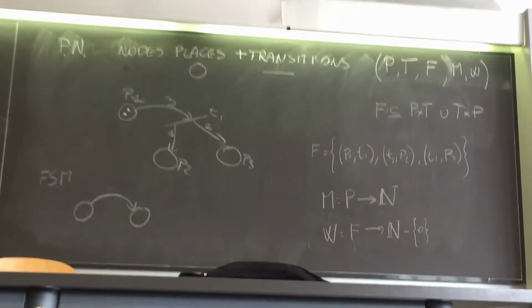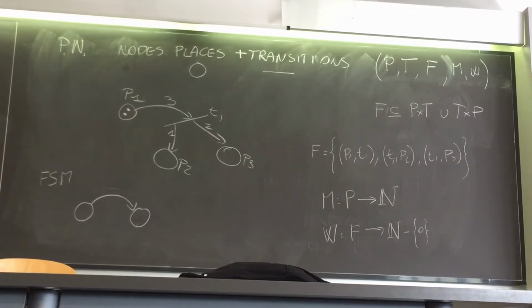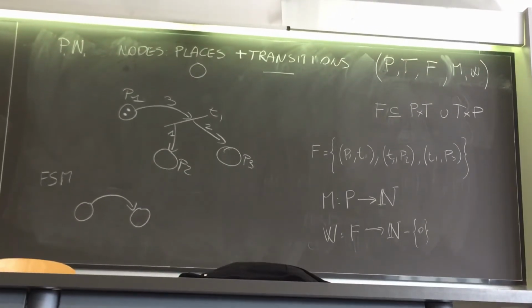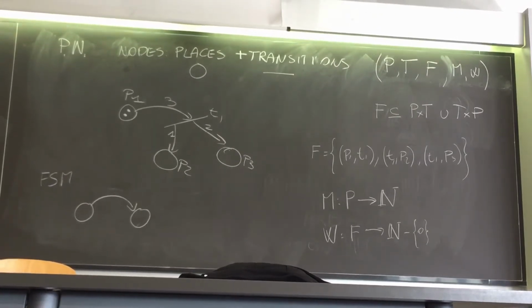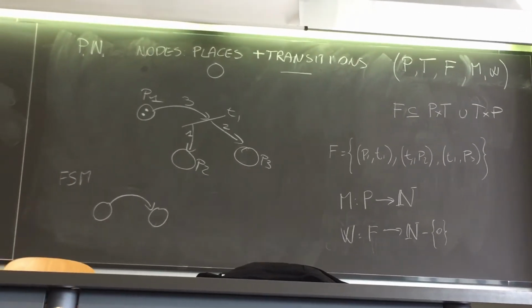On top of that, actually, I've not finished, because with automata, I would have finished in a few words. When you define a transition function, you are done. You say that there is just one current state, and then you change state through the transition function, that's it. Now I have to explain or invent how to play with these quantities to build an evolution of the model, to build a behavior of this Petri net. The behavior of an automaton is the set of arcs that you travel on. Now I have to define these rules.